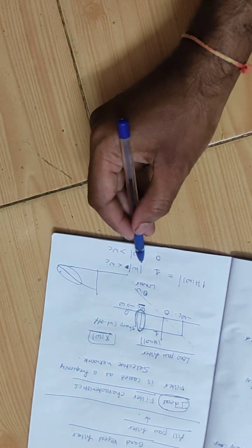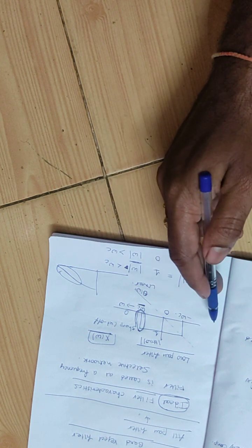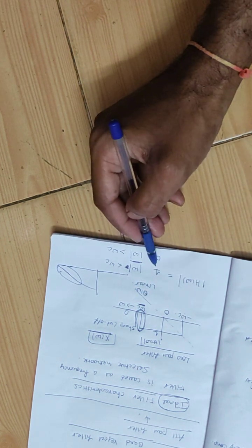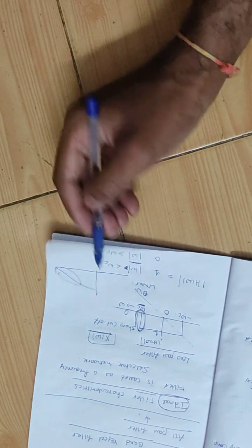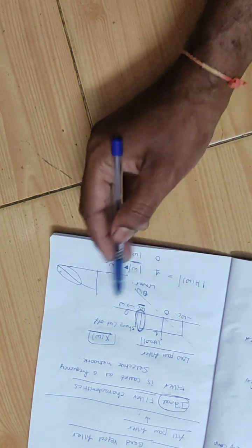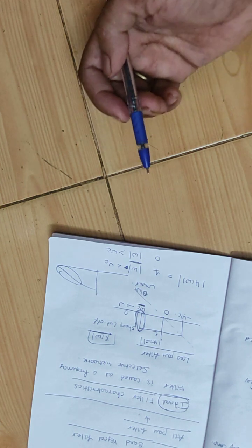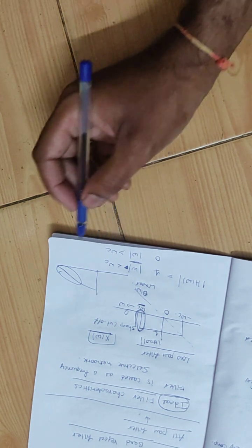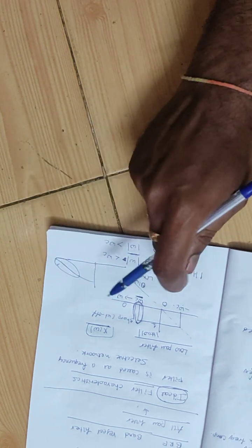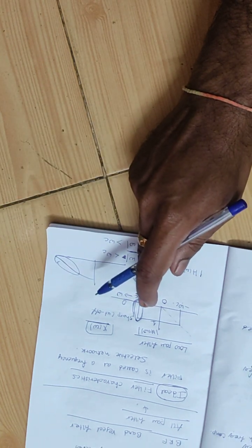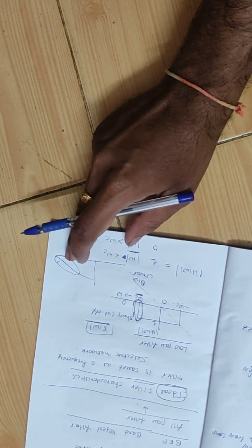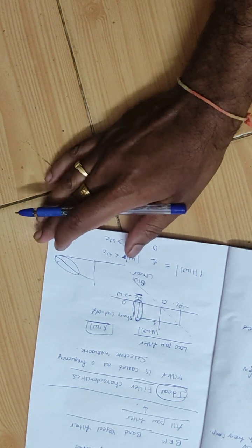Okay, that is, this modulus of omega means for minus omega and plus omega. From minus omega c to plus omega c, it is equal to 1, and beyond that, greater than omega c, it is equal to 0. I can write commonly like this. This is for a low pass filter, but practically remember that this kind of sharp cutoff will never happen for any practical filter. Practical low pass filter characteristics will be like this.